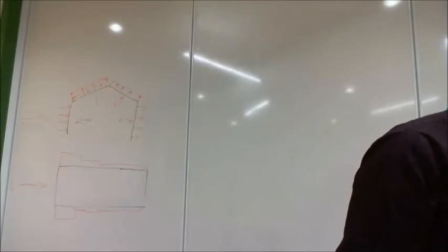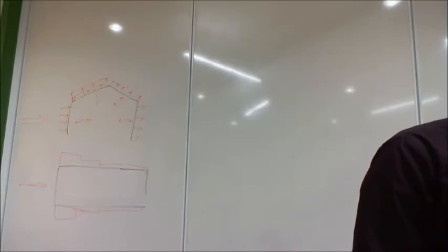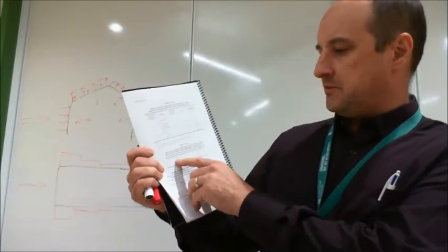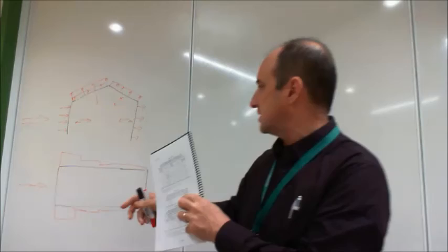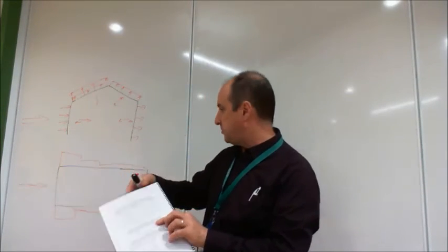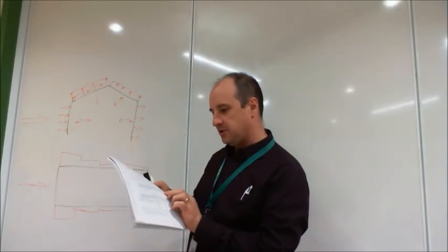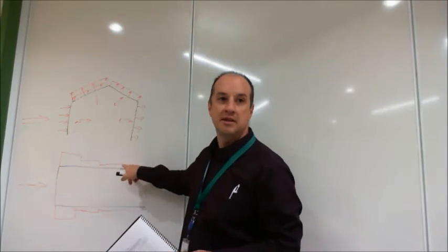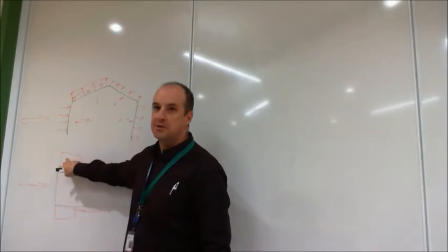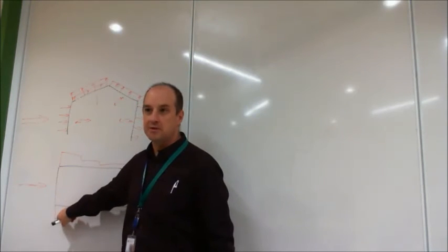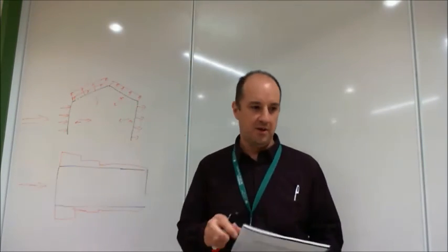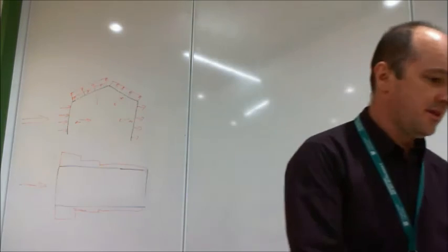So, walls, where are we? Side walls are table 5.2c. And from 0 to 1h, you've got minus 0.65, which is quite a high force. Then 1h to 2h is 0.5, 2h to 3h is 0.3, and then 0.2. And so what that's saying is, up at the upstream side of the building, you've got a lot of force pulling these walls outwards, and that force just diminishes as you go along the building. Okay? Again, we'll come to that soon.